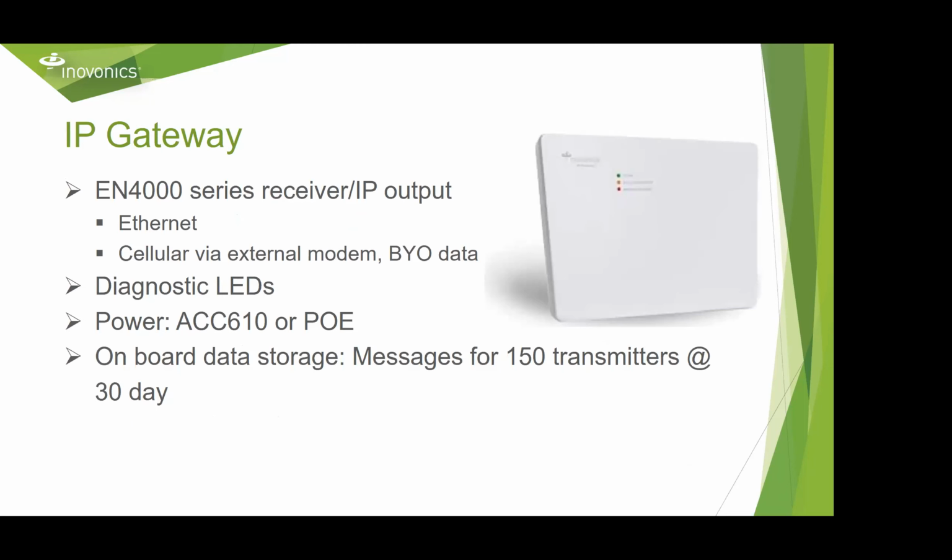Gateway itself, there's a few different things under the hood here. There will be some backup communication capabilities coming in the future, such as cellular. But basically, this is what brings the located messages to our server. You can go PoE or use our standard, I believe it's a 14 volt AC transformer, or 12 to 16, somewhere in there. There's some onboard storage as well. So that's the gateway.